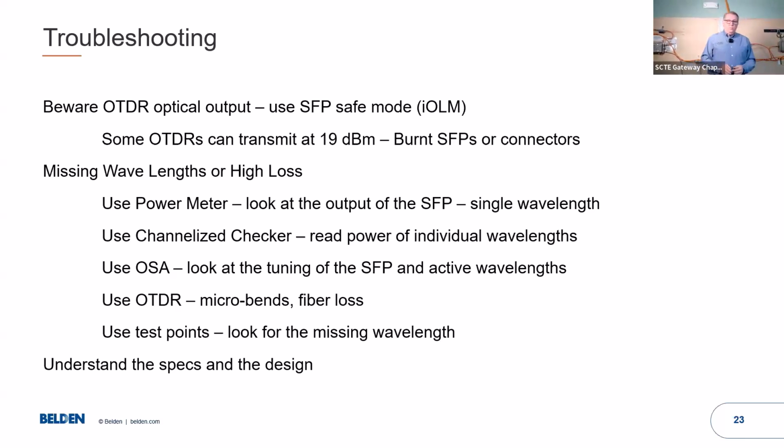OTDRs, troubleshooting, just like in regular fiber. But remember, the bends can impact one wavelength more than others. So the new WDM OTDRs can actually troubleshoot the wavelengths that you're having problems with. So those are important tools.